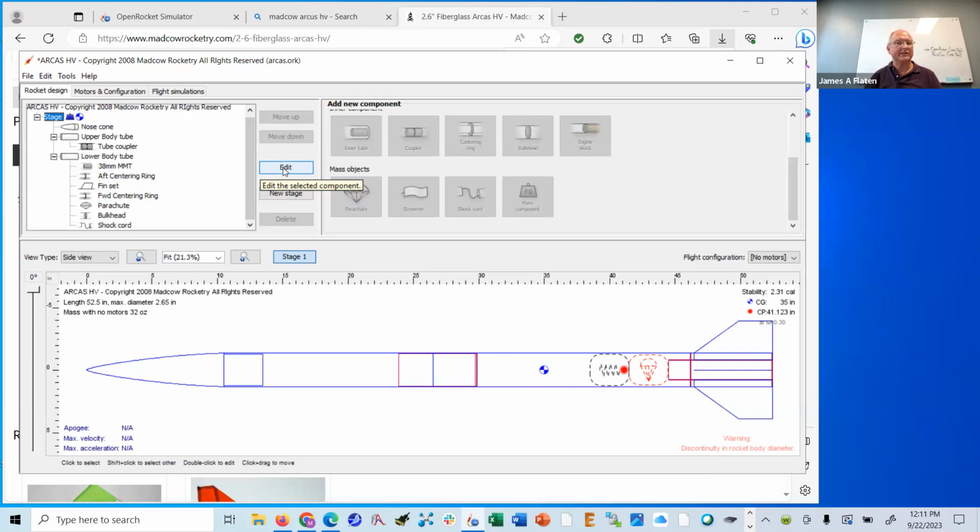When you build a rocket, usually there are things in the rocket that are not in the model, especially epoxy and stuff like that. So sometimes you end up with a slightly heavier, maybe slightly lighter rocket than you expected, and you can balance it on your finger and figure out where is the exact center of gravity, and you can override the calculations by the program to force it to use a specific mass and a specific center of gravity. But I think for design purposes in particular, it's good to leave the overrides off, and then you will have live calculations.